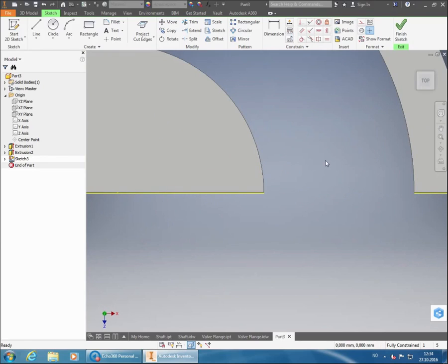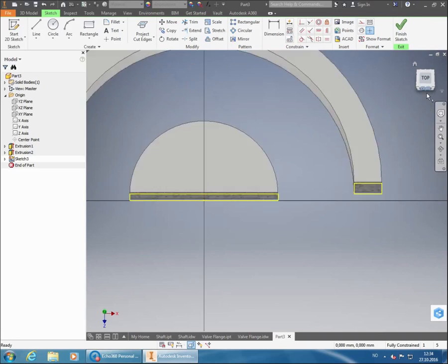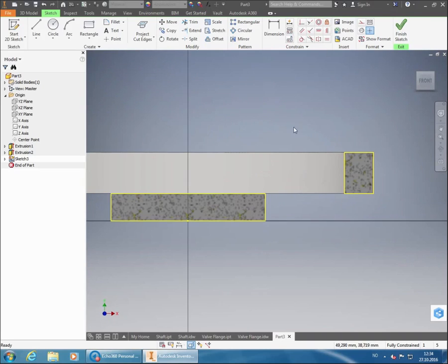So once I start my extrusion from this center plane and extrude both ways, we can see that I'm going to have an opening here between my extrusion and the disc there. It's not going to be a problem over here because my extrusion is just going to go into the material and fuse together, so that's going to be fine. But over here we will have a slight problem, which means that we have to take a little look at how it's been done in the compendium.